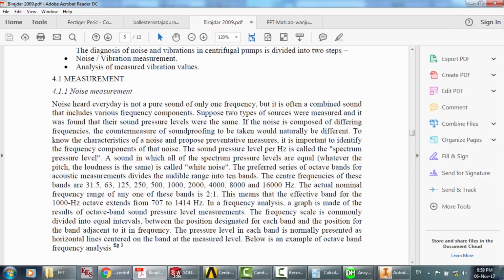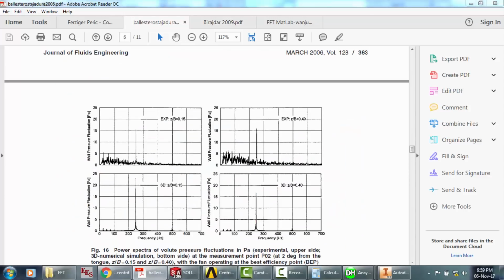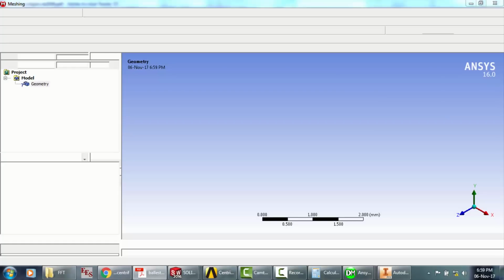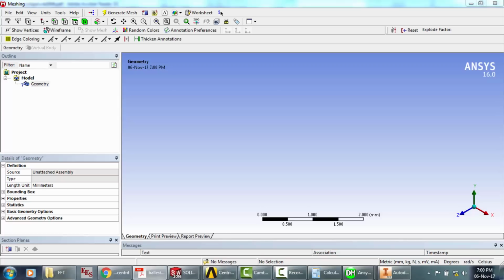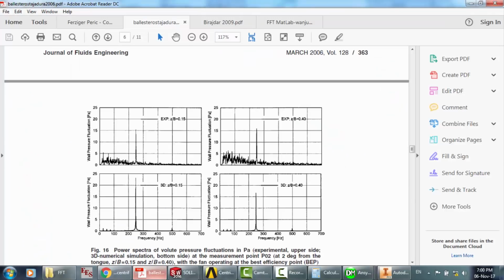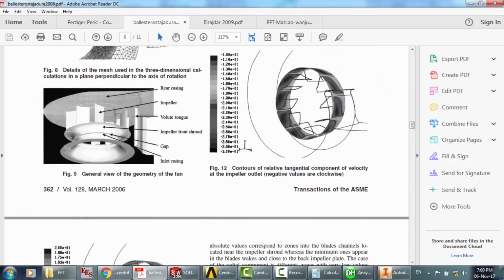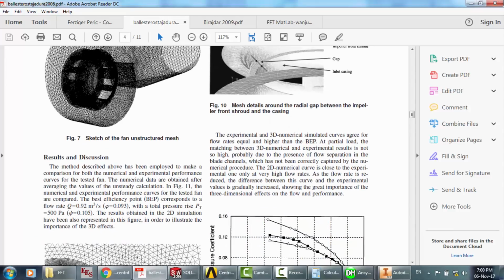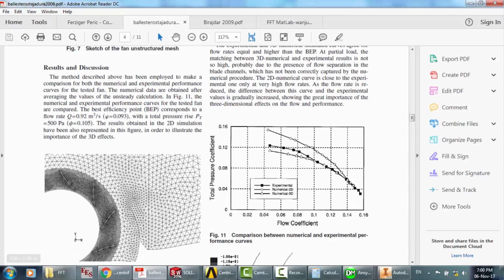The meshing is very important. It is a very important part for the complex geometries. Like I said many times, you can generate the unstructured mesh, but you have to carry out inflation around the blades to generate a structured grid, for the boundary layer or any other calculations that require structured grid. Or here unstructured grid, and now I'm going to show you how to make the inflation.